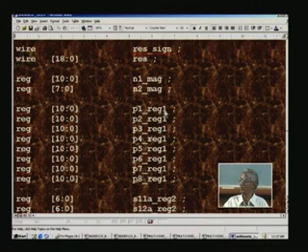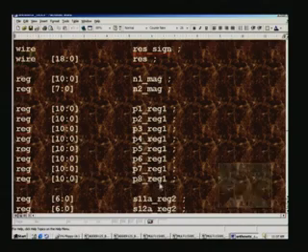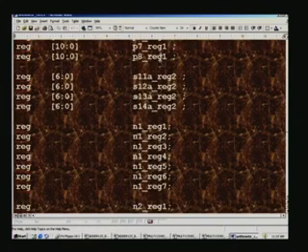For example, for clock 1, any registering you do for the partial product is given reg 1, which is the nomenclature adopted here, and similarly for the other pipeline stages. When clock 2 strikes, we will have intermediate results in reg 2, and so on.